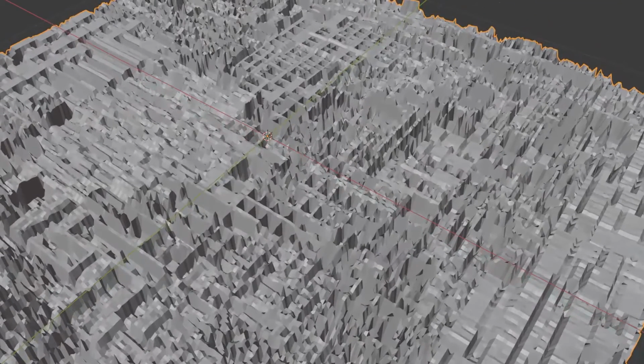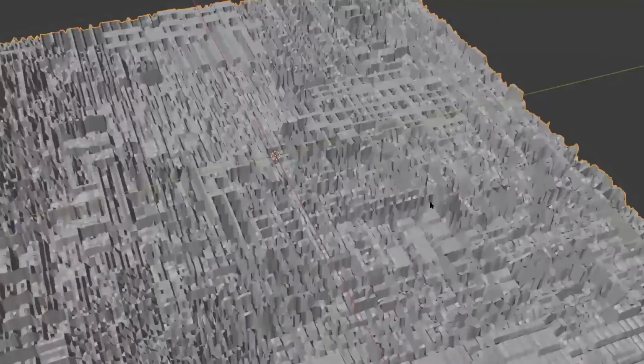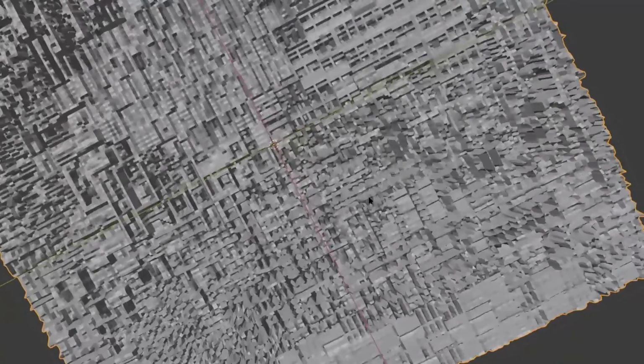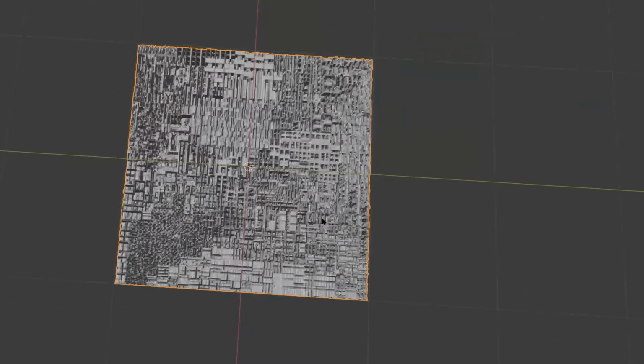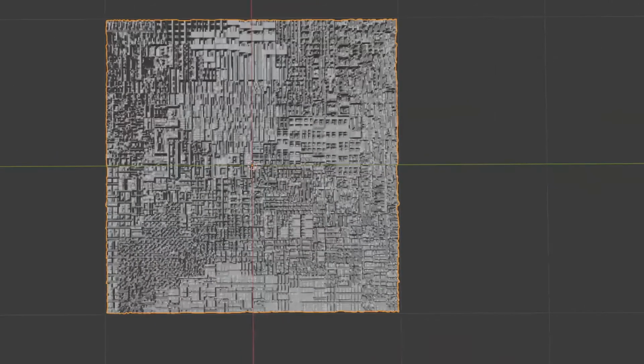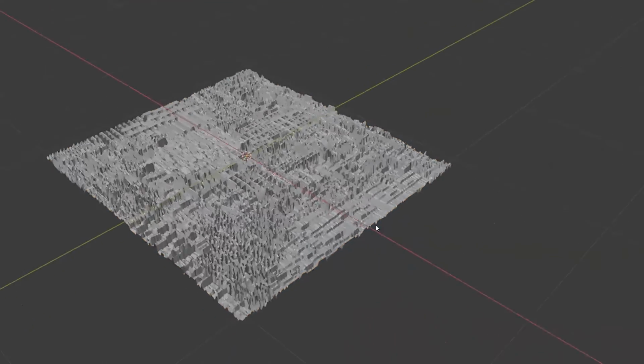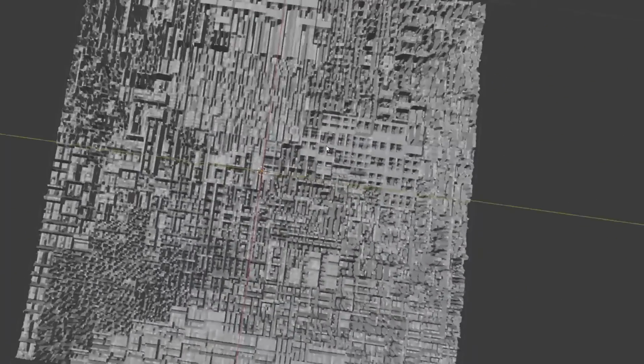If you want less height for your facade, you want to have it at 1. For me, because this is just a facade, I'm treating this as a facade panel. I'm just going to put it at 1. Okay. And once we've done this, we're going to hit apply here. Then your plane is now transformed into this displacement model.